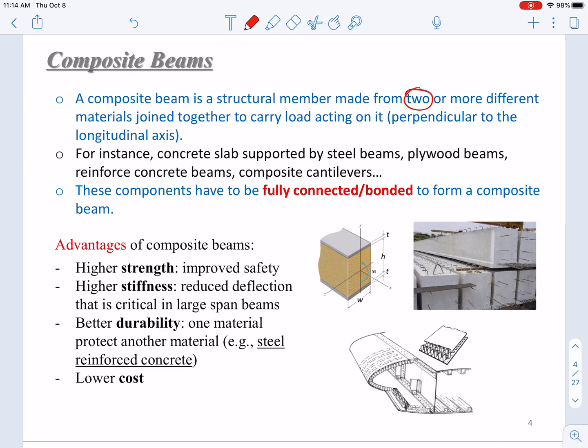So we leverage the ductility of steel to provide the overall ductility of reinforced concrete structural members. But steel is easy to corrode when it's exposed to moist air, while concrete will not corrode. So we use concrete to wrap steel to protect it from being corroded.